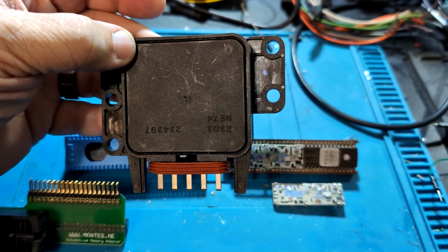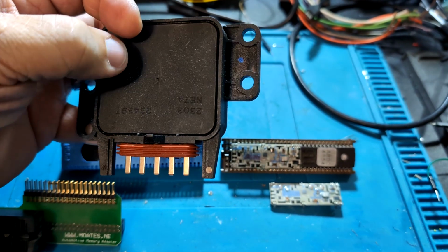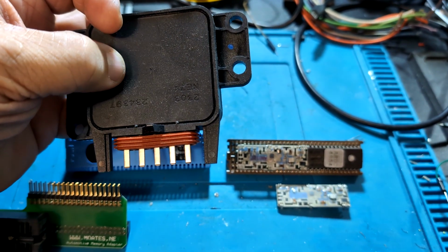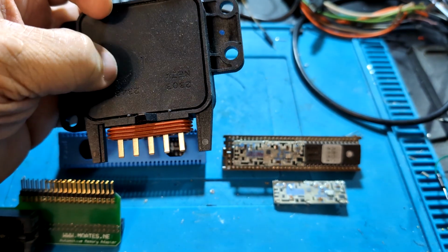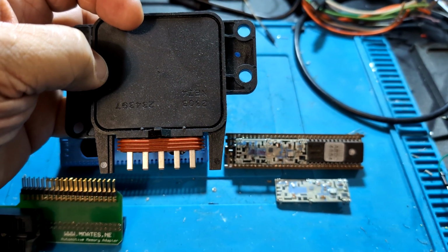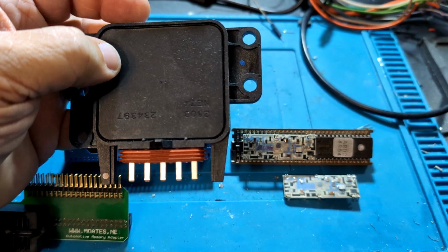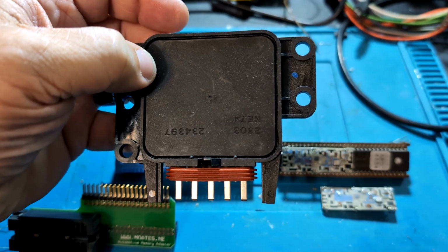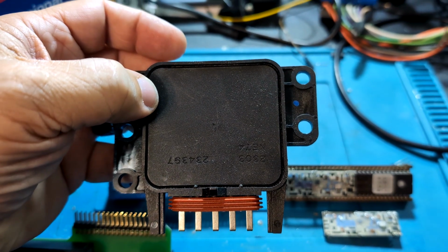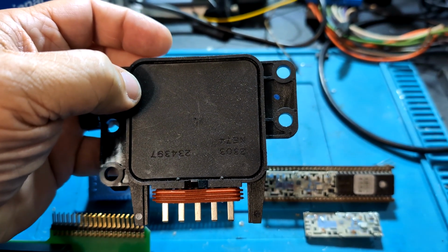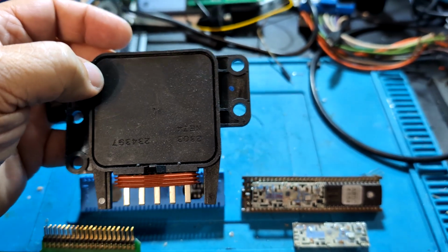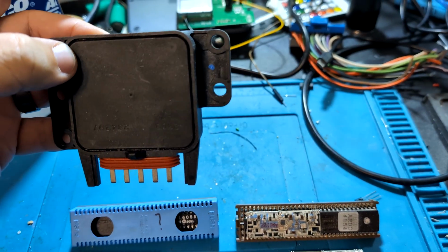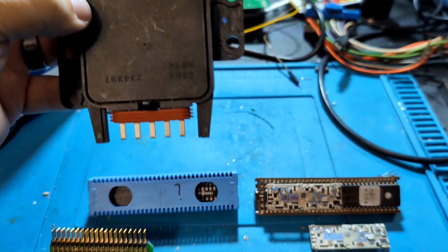The knock sensor went to this. This filters the signal from the knock sensor and then sends a signal to the ECU. The ECU then processes that and decides what to do in terms of retarding the timing if it senses knock, etc. So this is what exists on the mass airflow cars.